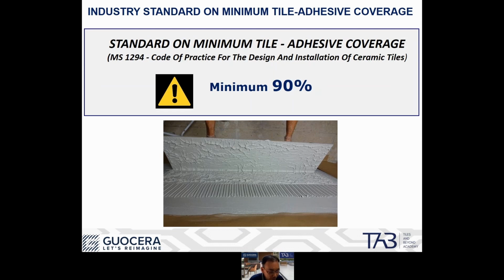Now, this is the one. The question was asking what is the minimum requirement of the tile adhesive contact. MS 1294 recommends that the coverage of tile adhesive be a minimum of 90%.